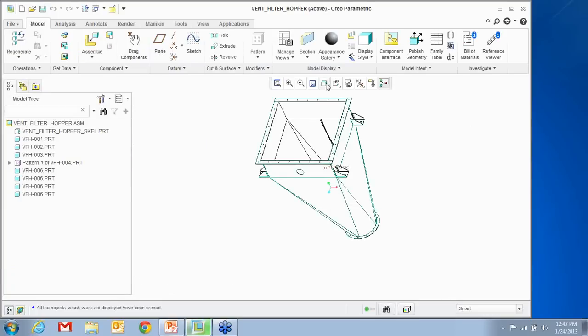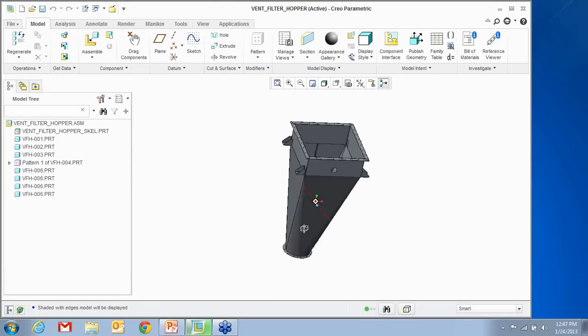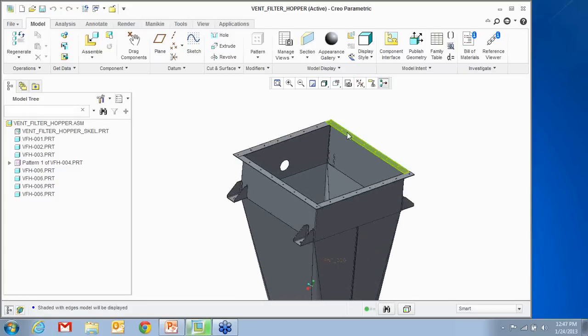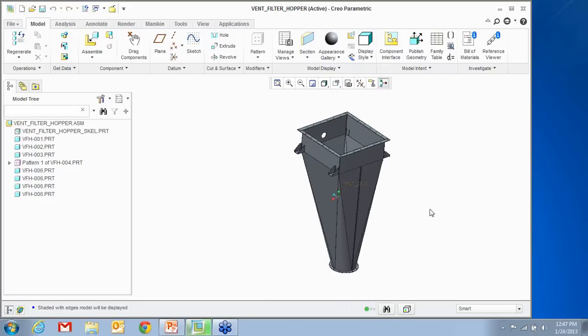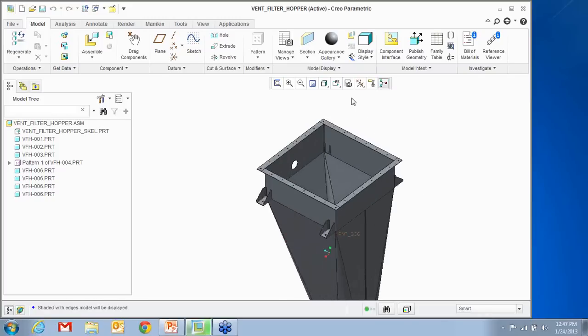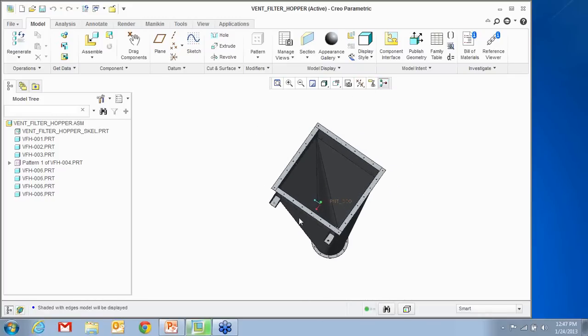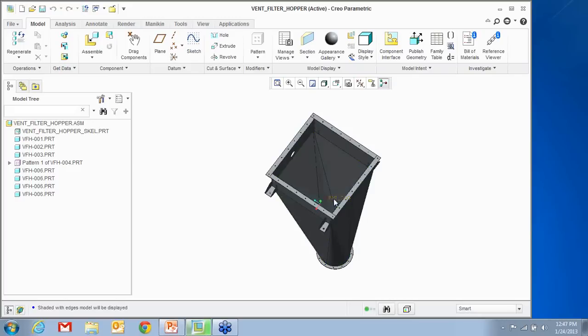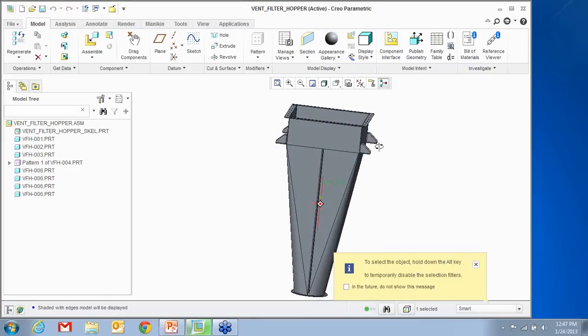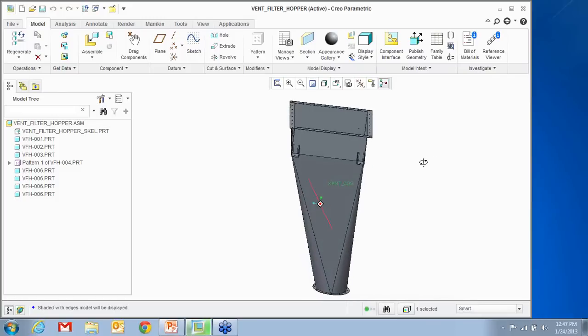Another thing is weighted links. Now say for example, I have this little assembly and I have a huge load sitting on these four surfaces on the top of it. Now I want to see the stress that's applied towards this little sheet metal part or assembly. Now instead of modeling the whole load on top of it, you can find out the center of gravity point. See that CG point right there? You can find the CG with the load on and create a point over there.